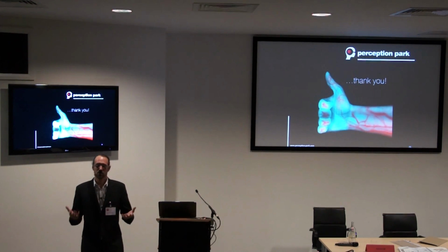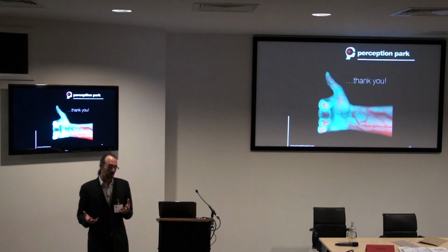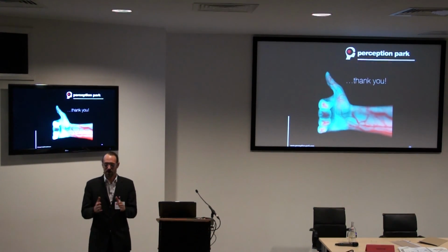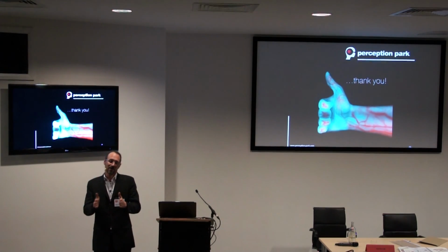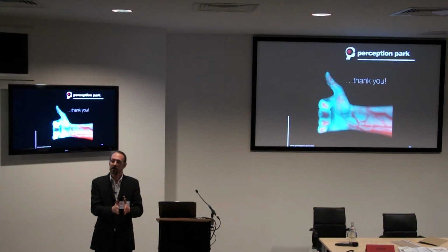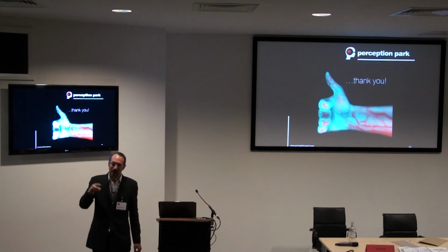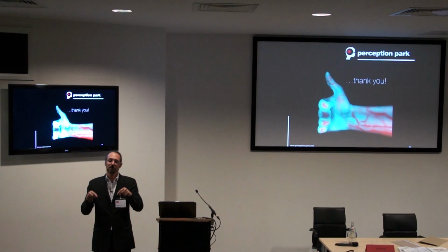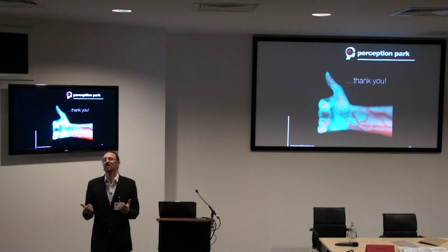If you are a data processing person, it might be interesting to have 8 nanometers optical resolution and 2 nanometers signal sampling, because then you have oversampling. By applying filtering, you don't influence the optical signal and you are able to reject the noise of the sensor. That's an interesting aspect in this circumstance.